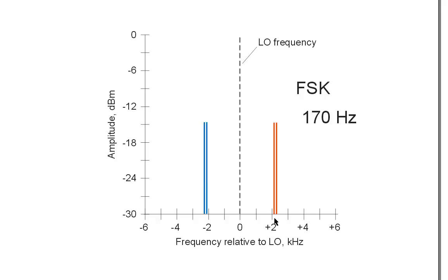These frequencies are standardized to produce audio frequencies in ham radio receivers, and the standard frequencies that I have seen used are 2125 Hertz for the mark and 2295 Hertz for the space. Those are the audio frequencies. Notice they differ by 170 Hertz.